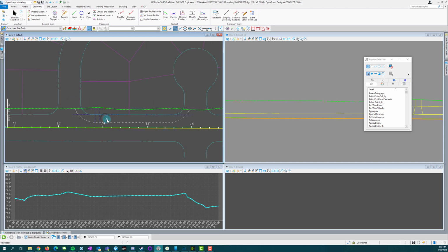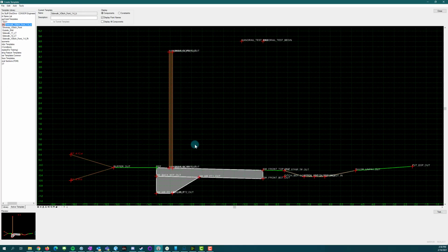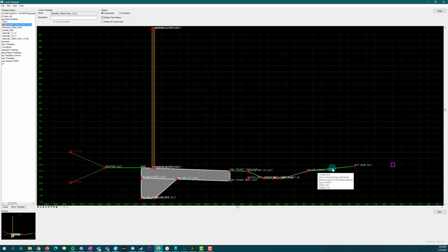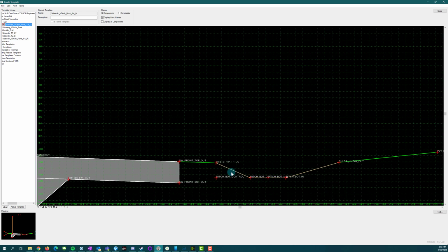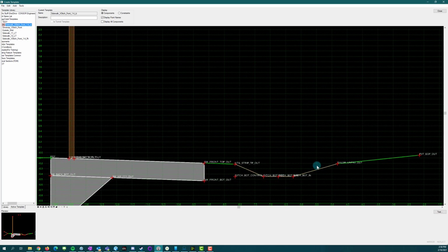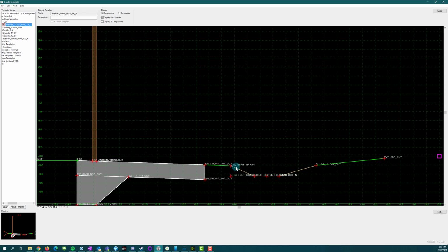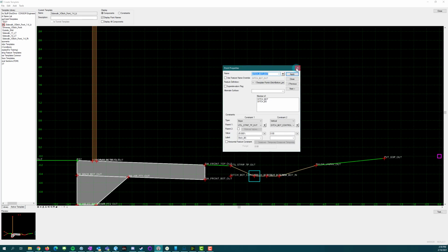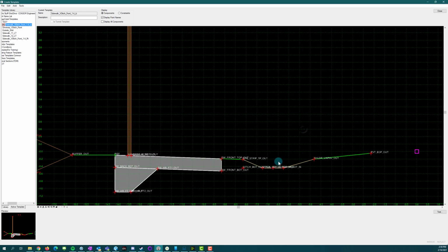The next thing we need to do is look at the template that we're going to be using. So I'm going to open up my template library here. And this is the template that we're looking at. It's got a 2 foot 6 inch unpaved shoulder. We've got a 1-on-4 slope down to the ditch. It looks like this might be a 1-on-3. So these slopes will depend on the design speed of the adjacent roadway and the clear zone that you need to account for. This slope is, yeah, that's a 1-on-4. This looks like it might be a 1-on-6 actually. Yep. So that's what we have here.